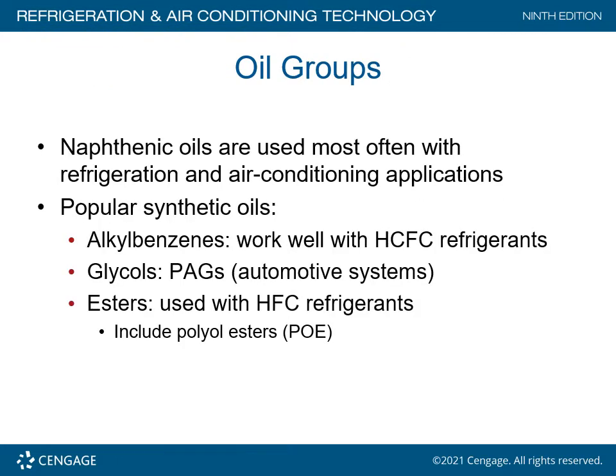Oil groups are divided into naphthenic oils, which are most often used with refrigeration and air conditioning applications. Popular synthetic oils are alkylbenzenes, which work with HCFC refrigerants. Glycols, which are PAGs, are strictly automotive.